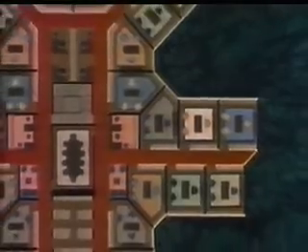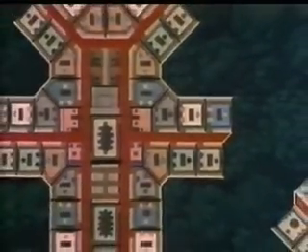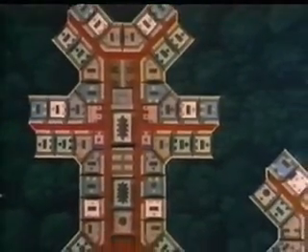But now the ratio of exterior wall to the interior is increasing, and this is a problem because exterior walls are one of the most expensive elements in a building. So to keep the exterior wall at a minimum without sacrificing volume, we developed 2 different office shapes. They are the same size exactly, but one is a square and the other is a wedge. The final layout houses a total of 80 people in approximately 22,500 square feet.